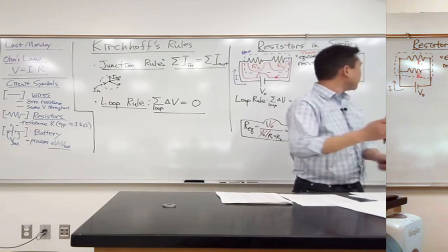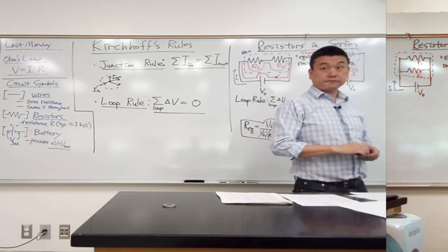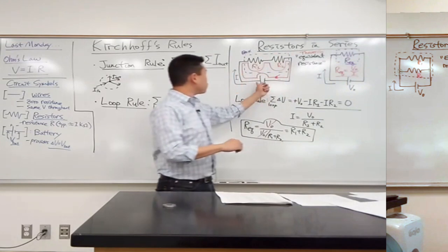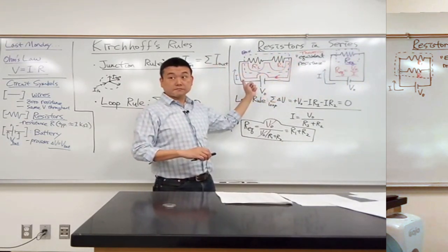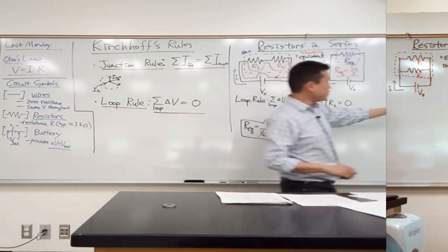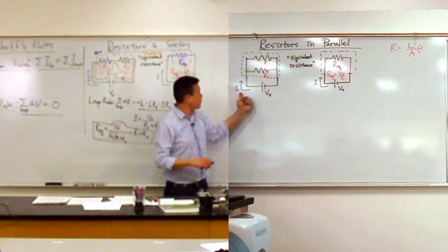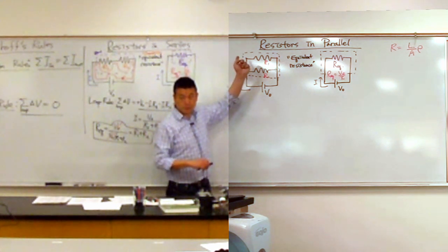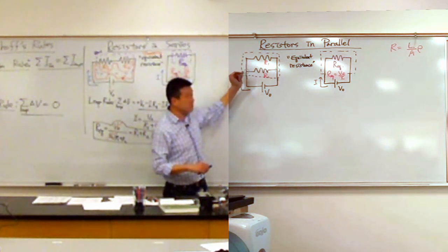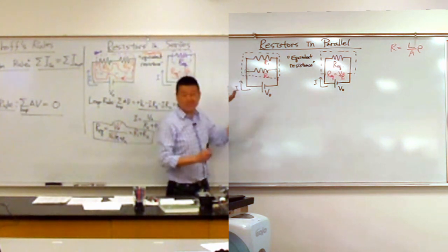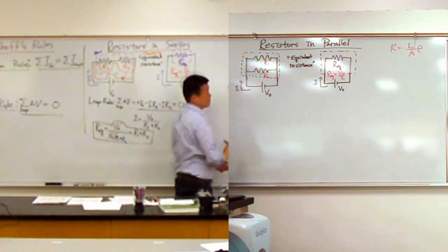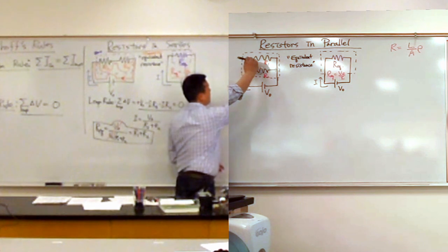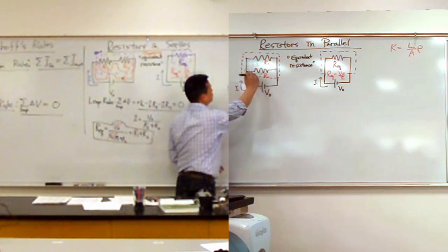Yeah, I'm kind of hinting at it, but I need to label my current. So here, this current was the same current throughout the entire circuit. Right? Here, can you say this current is the same current throughout the entire circuit? No, once you come across this junction, you face a choice. The current could go up or to the right, which means it splits off. There's going to be a current that goes here and a current that goes here. So let me label them I1 and I2.